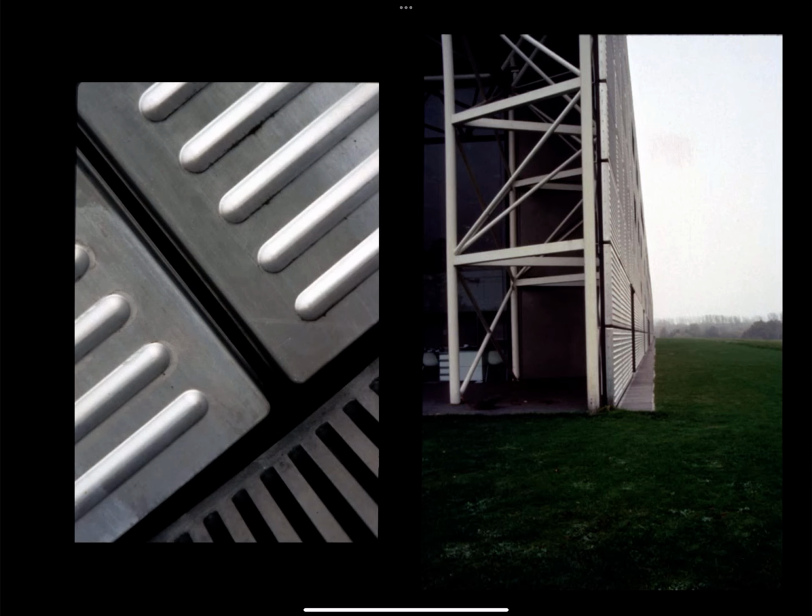So here you see a couple of the aluminum panels close up. You see the ribbed surface. You see the black neoprene gasket that seals the joint. And then the grating at ground level. So the water comes off the building and all of the vertical joints, and it drops into a trough in the ground below this grate and is carried away. So again, there are no rainwater pipes or conventional gutters in this building.